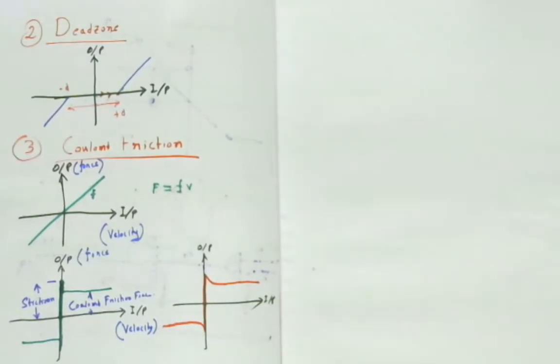And if you want to design your control system for these kinds of problems, you have to deal with this Coulomb friction force and stiction force, but you cannot have a transfer function because of this kind of nonlinearity. So what to do is to find the describing function. However, I have not started explaining what the describing function is, but let me tell you, it is the method which is basically used to represent this kind of nonlinearity. And if you have a representation of a nonlinear system, you can now find the stability, and you can design your control system accordingly.